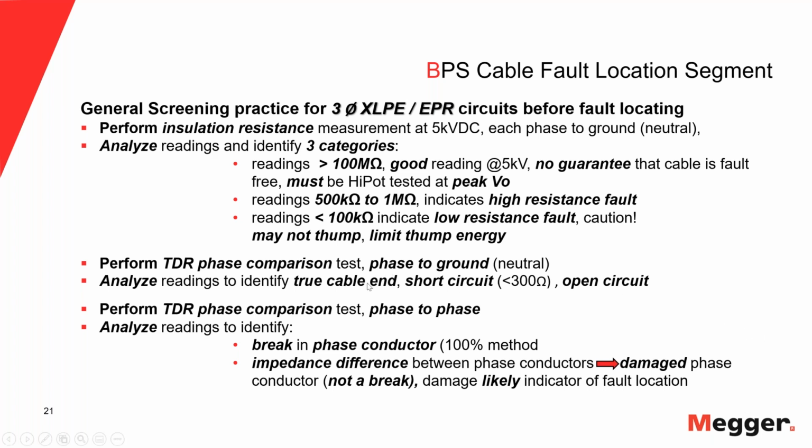If we cannot verify the cable end, then we might have a short circuit or an open circuit in the cable. And the distance to those is where that short or open circuit is located, which means there shouldn't be an open or short circuit in any of these cables. That means most likely that's where a fault is, okay? It's a first indication that there's something wrong with the cable if we cannot ascertain the true end of the cable.